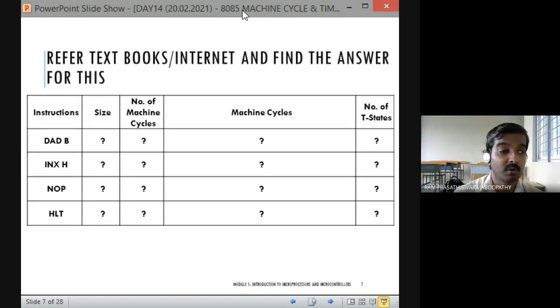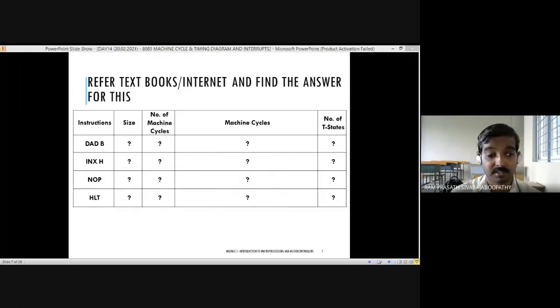Also note down one more instruction, the call instruction. Fine. Similarly, conditional call. Say for example, take C: call if carry. What should come next to call? An address must come. Fine. CC ADR. Similarly, take RET. Fine. So consider this instruction also. RET.